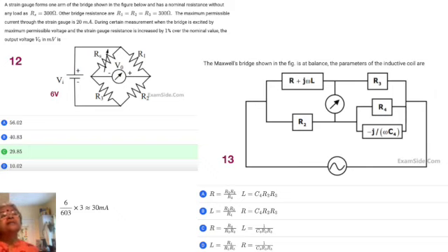And as the resistance increases, the current decreases. So we have the maximum value, and so we also have the maximum voltage, as given by 20 milliamps into 300 plus 300, two resistances in series, which is 6 volts. That's how you get the maximum voltage of 6 volts.